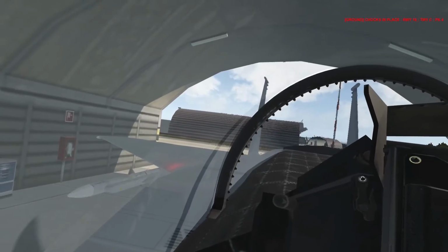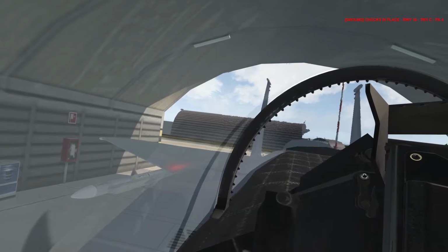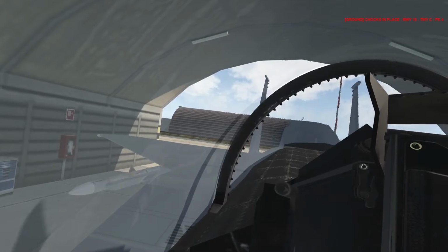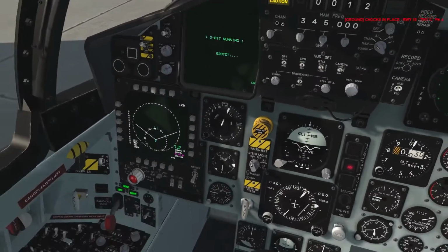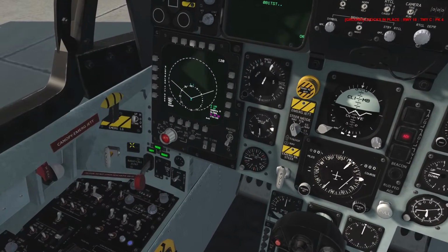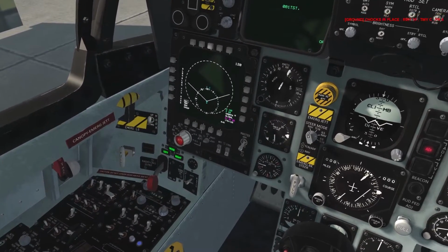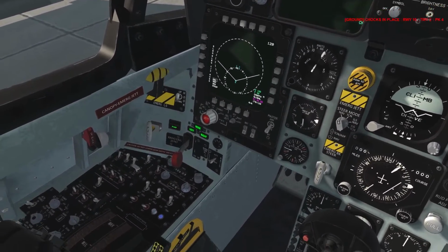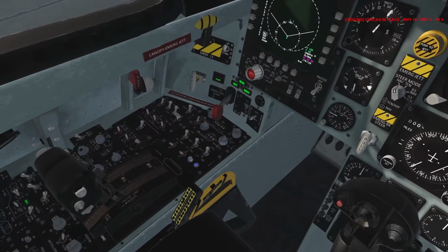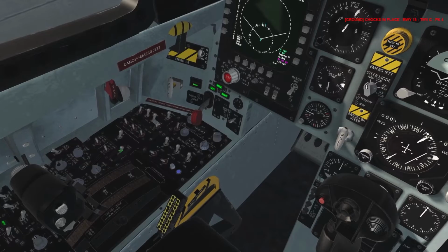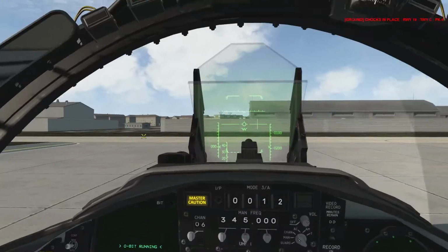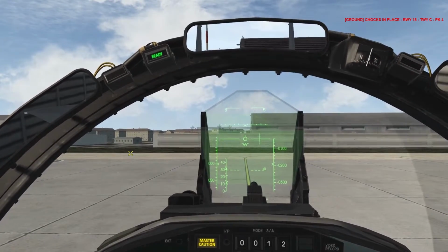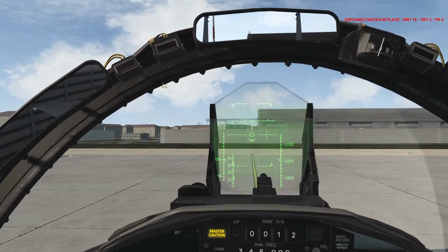We can check the speed brake. So full up and fully retracted. That's a good check. The flaps, we've got retracted or down, and amber indicates in transition, green indicates set or extended. Flaps set. The slipway door, if air refueling is planned, so that's the switch there. It's not animated on the 3D model yet, but we do have a ready light there. So that's a good check.